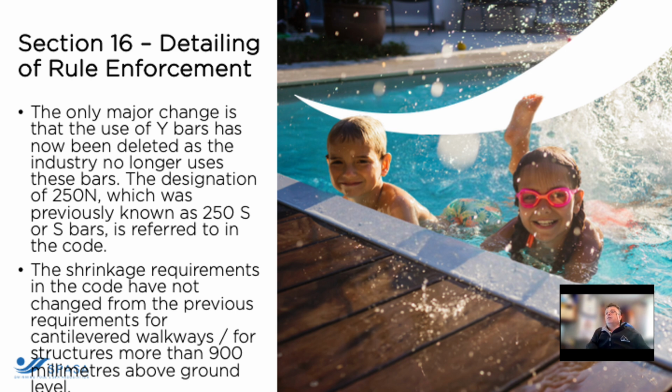Section 16, which is the detailing of reinforcement. The major change is the use of Y-bar has now been deleted, as the industry no longer uses these bars. I see this in documentation when I'm involved in various cases where documentation has not been updated. Now the code is actually specifying it. It's not giving you a choice. You can't just leave it on there and think, oh well, if they can get it, that's great. No, it's not to be used, well, not to be specified. The designation of 250N, which was previously known as 250S or S bar, is referred to in the code.